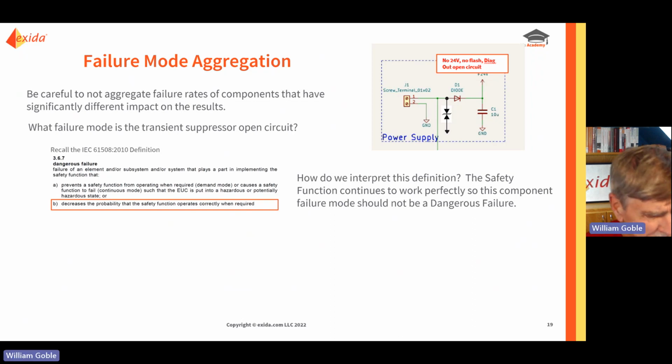It sure doesn't look like a good idea. You might think you're being conservative, but that's way too conservative when you realize that two components have to fail. If you have a 10 to the minus 8 failure rate for the open circuit transient suppressor and a 10 to the minus 8 for another component downstream, if A and B fail, you multiply, basic rules of probability. 10 to the minus 16. Now, come on, we don't have nearly enough decimal points in our numbers to account for that.